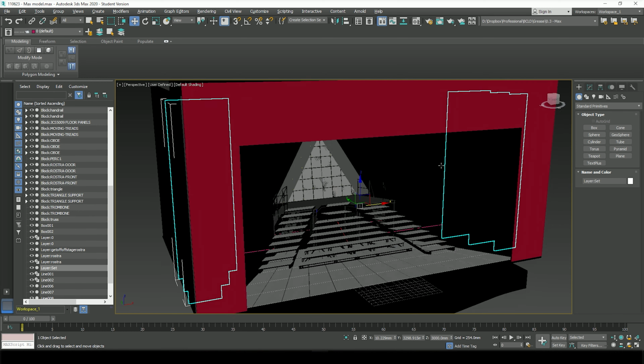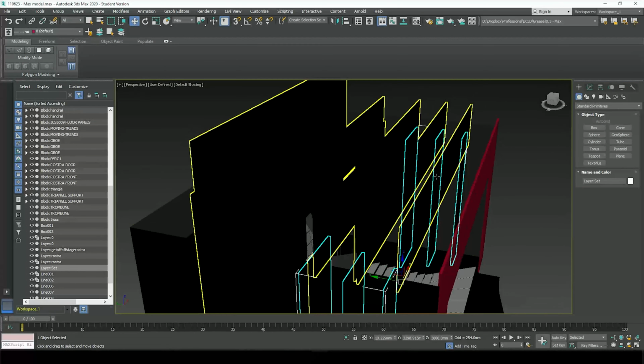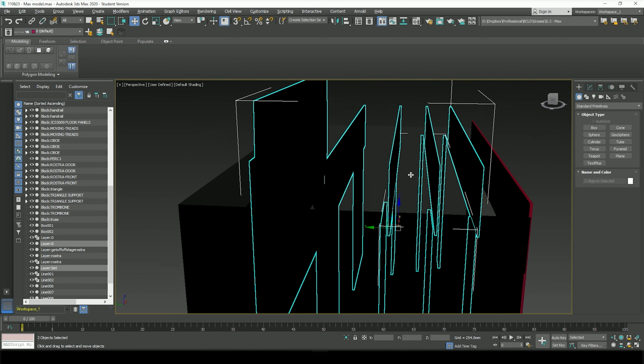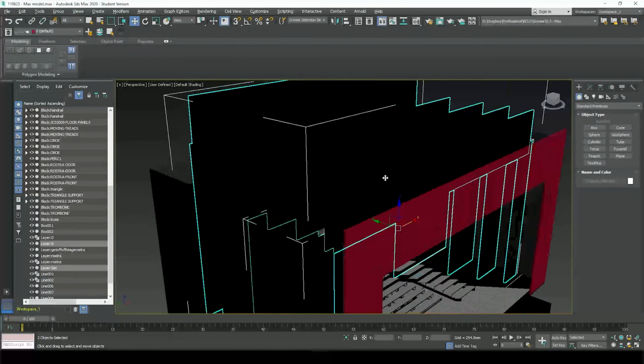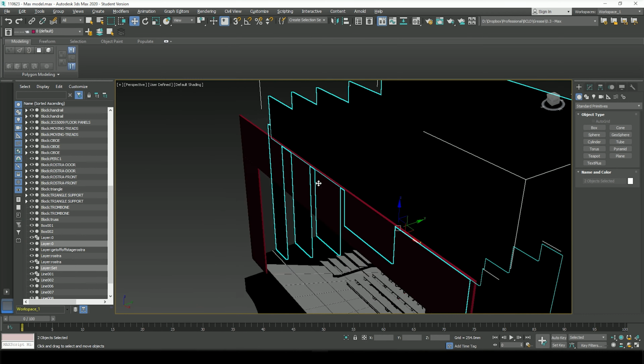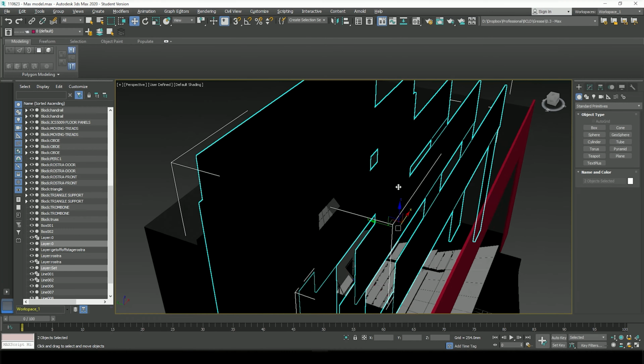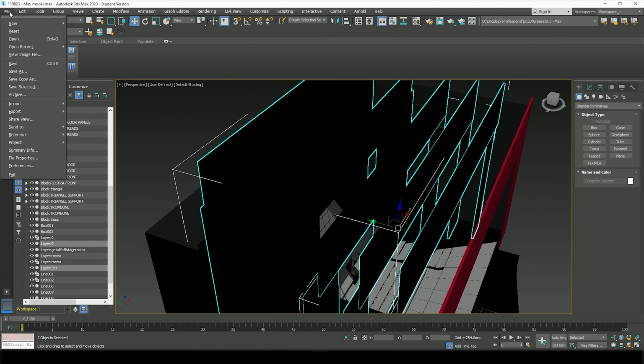In this case, all of my borders and my legs, they don't have textures, they're just black. And they'll always be black. I don't need them to have any other information on them. So I am going to export those as a DWG. So I'm going to select them, go File, Export, and this time select Export Selected.